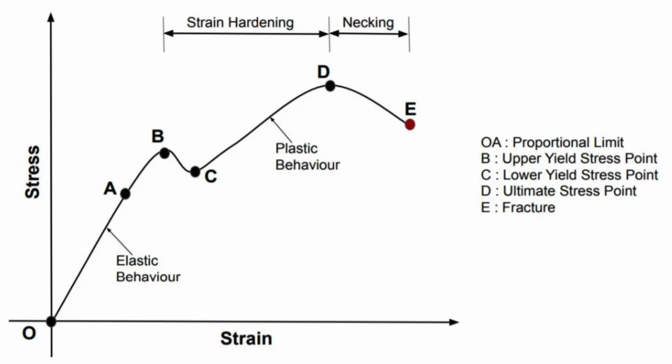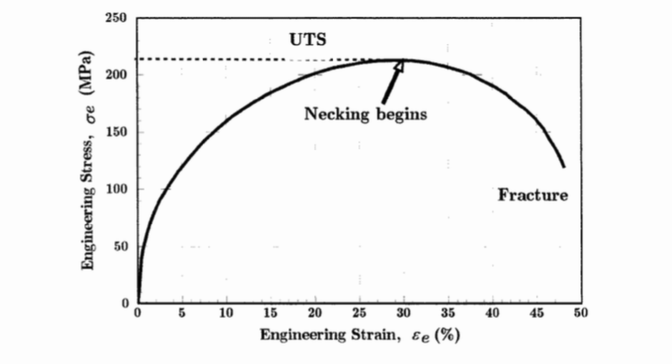This is the stress needed to induce plastic deformation in the specimen. Since it is often difficult to pinpoint the exact stress at which plastic deformation begins, the yield stress is often taken to be the stress needed to induce a specified amount of permanent strain, typically 0.2%. The apparent change from strain hardening to strain softening is an artifact of the plotting procedure, however, as is the maximum observed in the curve at the ultimate tensile strength, UTS.